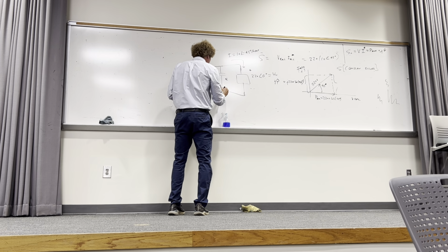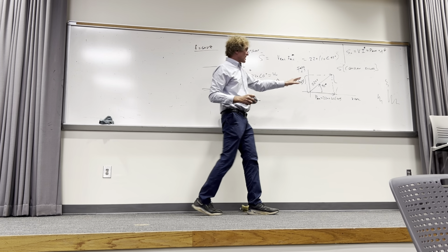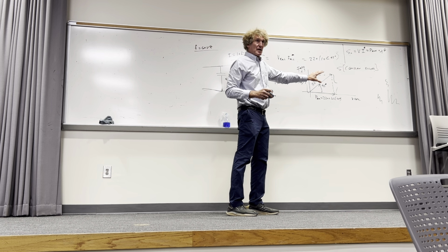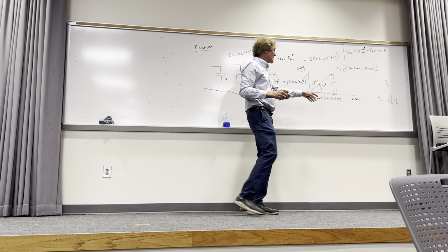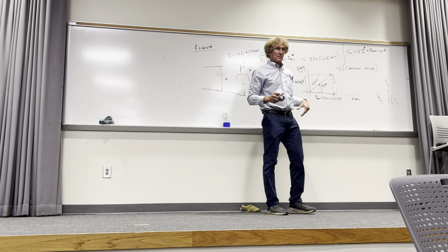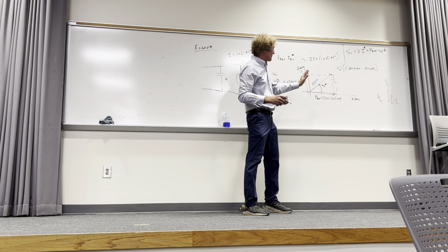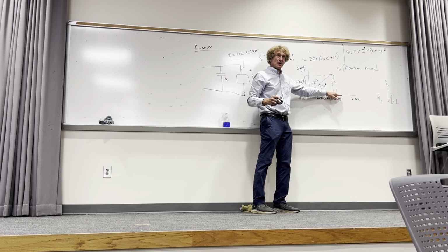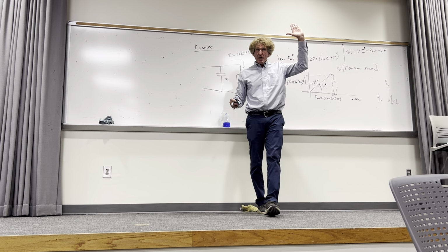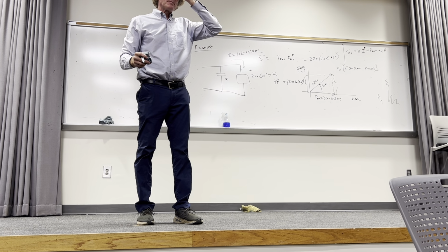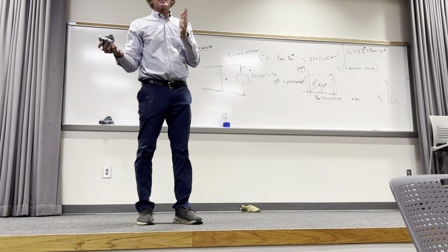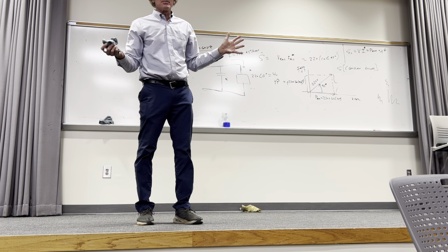So I have this drawing that I've shown you. And now I'm going to talk specifically about a capacitor that would eliminate the reactive component. Right? And what would the power factor be if all of a sudden all the power was real? Class? It's 1, isn't it? The cosine of 0 degrees is 1. How many understand that? Please make sure you keep up with this, or when I start discussing this, you're going to be left wondering what I'm talking about. You have to stay current on this stuff or you can get terribly confused.